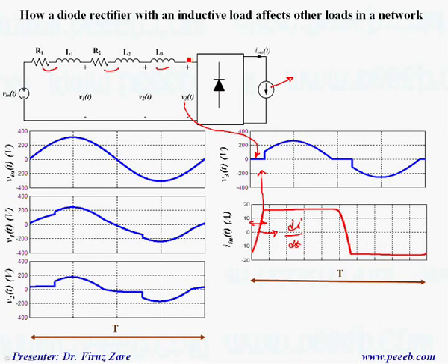So if we have a device connected to this terminal, this terminal doesn't get a pure sine wave. That means if we have a high power diode rectifier with inductive load, we may disturb the power system and change the power quality.